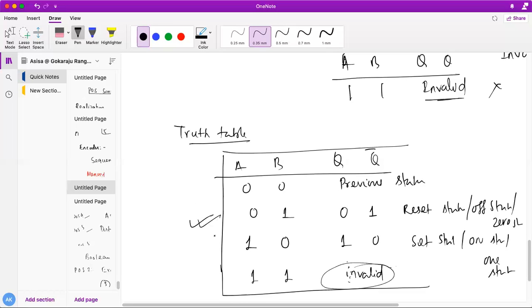You can see what I am doing here. Actually, whatever the desired value, the circuit holds the previous value; it holds my output. Here the desired value 0 is stored, or 1 is stored. My desired value is getting stored. Whenever I need, I give a equal to 0, b equal to 1, I will store 0. Whenever I want to store 1 in my memory element, I give a equal to 1 and b equal to 0. Okay, do you all understand? That's why it's just a basic memory element. So the basic memory element is also called the latch. This is also called the latch. Okay, do you all understand?